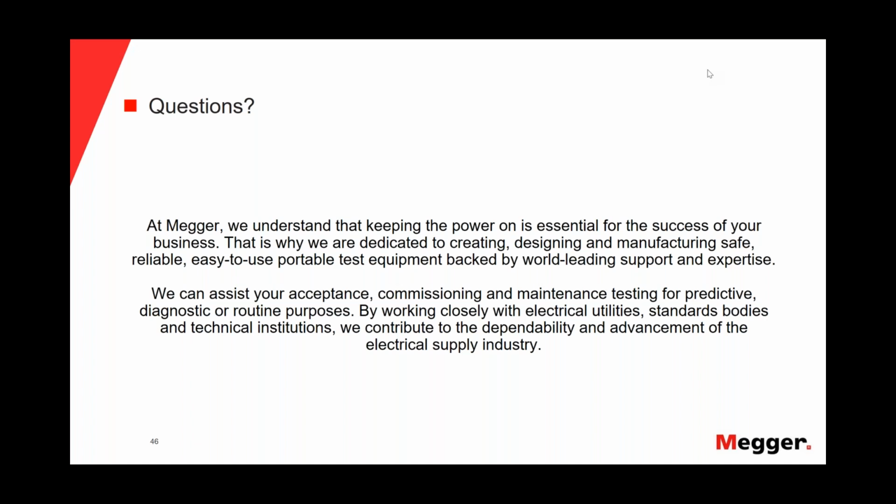So there are defects that react differently, and in that regard, I think power frequency is overall the preferable method, because it eliminates this potential masking of defects by using the 0.1 hertz frequency.